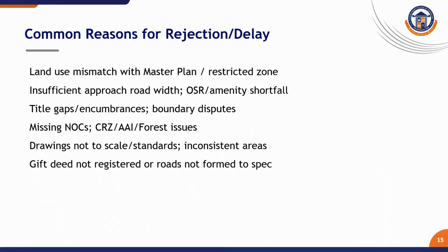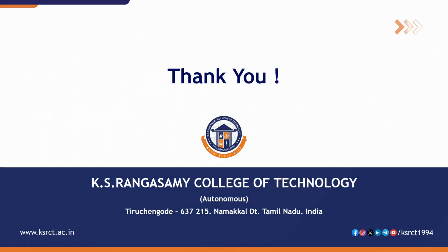Finally, being aware of the common pitfalls can save time: land use mismatch with the master plan, insufficient approach road width, shortfall of the OSR or amenity space provisions, gaps in the title, and missing NOCs. These are all common reasons for rejection or delay.